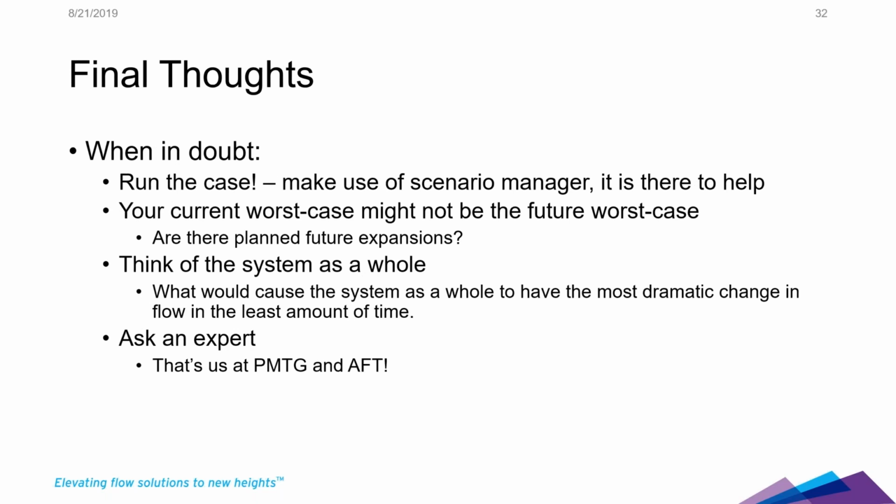It really isn't that difficult to make multiple scenarios, multiple scenario trees. If you look at it logically, if you lay out a plan of what cases you're going to look at before you run them all, you can lay out your basic system and then create this whole tree where you look at different fluid types, different valve closures, different arrangements, different set points, and run all of them. And once you have your base system down, that's the hardest thing to get together, getting your basic system laid out. Once you have that done, adding more cases sometimes isn't the most difficult thing to do.